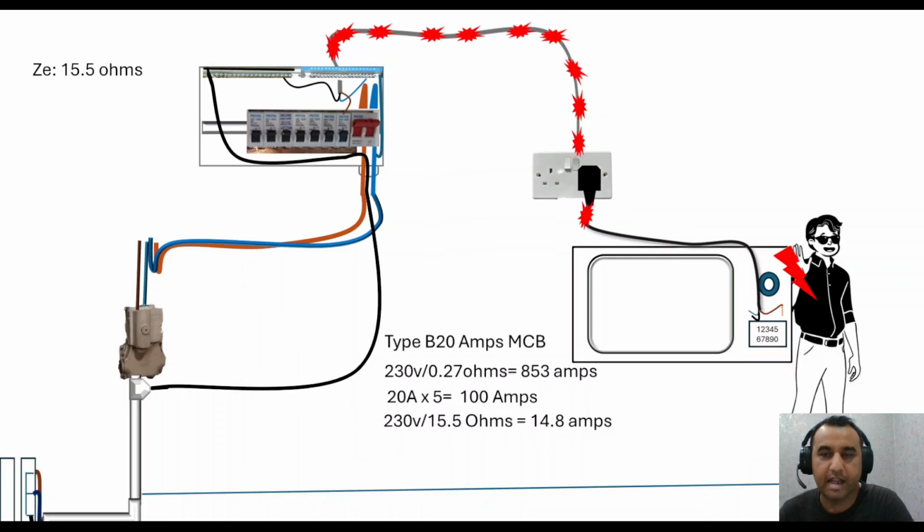Let's go to here. Okay, this is the worst case scenario. We've got a ZS value here because we've got a loose connection, a rusty system, and it's not giving a very good ZS value. It should be 0.8, but it's quite high. There could be any reason, the problem could be here, or it could be back there. So that's why we can't achieve 0.8 in this situation.